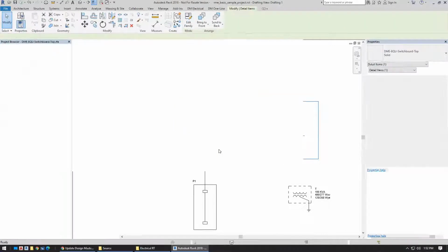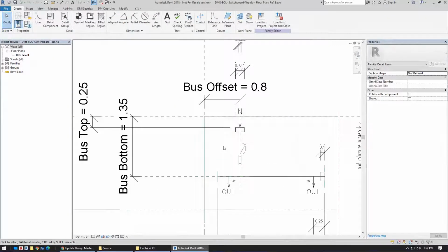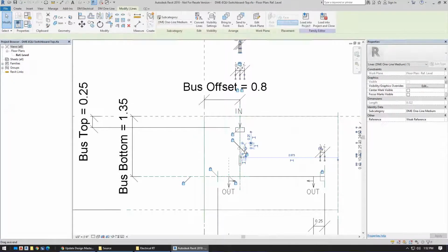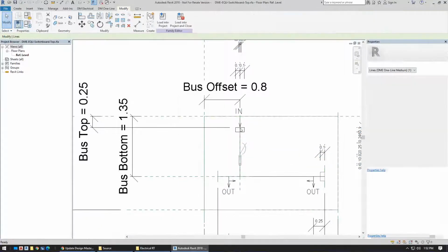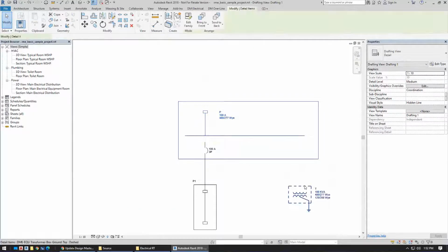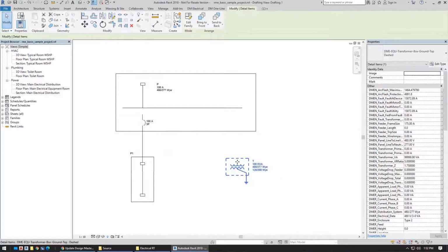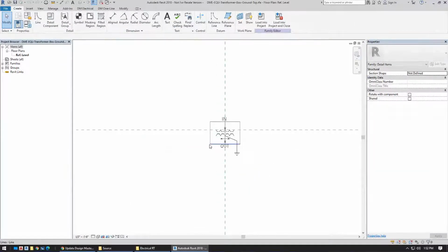And just, again, be aware, it's all using standard Revit functionality. It's a little bit tricky to get it all worked out, so you can kind of take a look at what we did. You can obviously see there's a lot of stuff going on in these families. You can use ours as a basis for working, or you can make your own. If you are making your own, a lot of times it can be simpler to just take something like our transformer, which doesn't have all of those fancy control points built in.